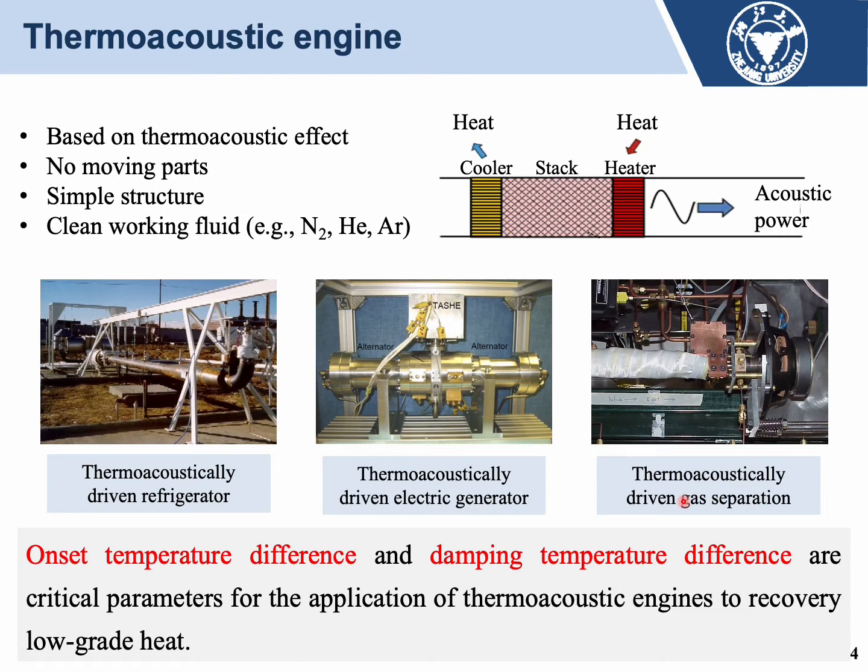In thermoacoustic engines, onset temperature difference and damping temperature difference are critical parameters for the application of thermoacoustic engines to recover low-grade heat, where onset temperature difference is the lowest temperature difference to trigger thermoacoustic oscillation, and the damping temperature difference is the lowest temperature difference to maintain thermoacoustic oscillation. Therefore, many efforts have been devoted to decrease onset and damping temperature difference.